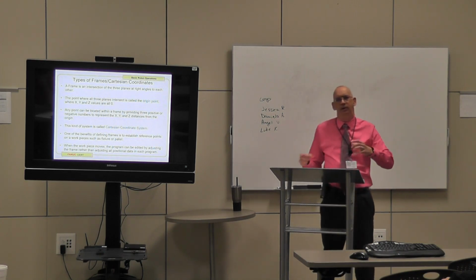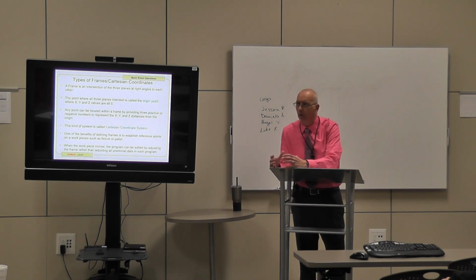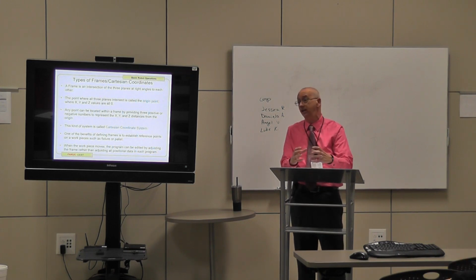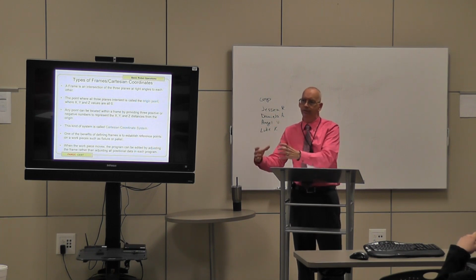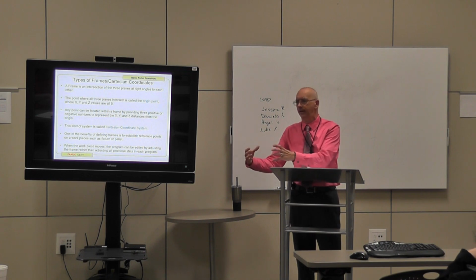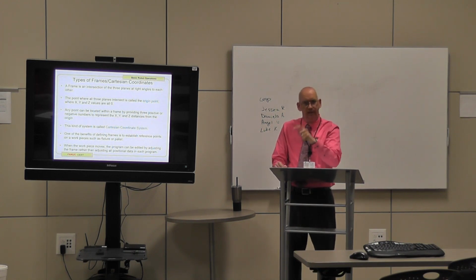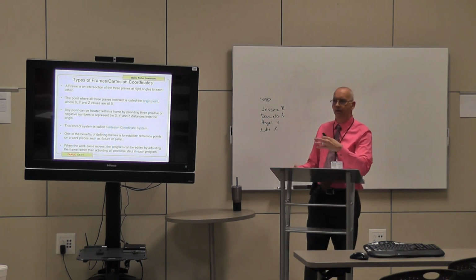So it does benefit using user frames, because if I have to move my frame, or we get a modification, instead of having to go through and change all of our points, say our jig got moved 2 centimeters or 2 inches this way, we can now do offsets in our program to make that happen. We don't have to go in and change every single one and touch up every single piece of data. That's one of the benefits of having user frames.